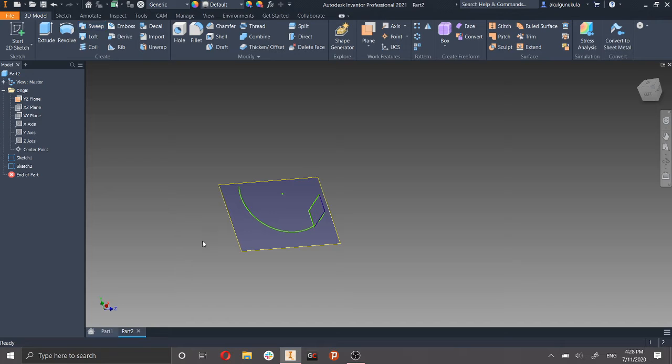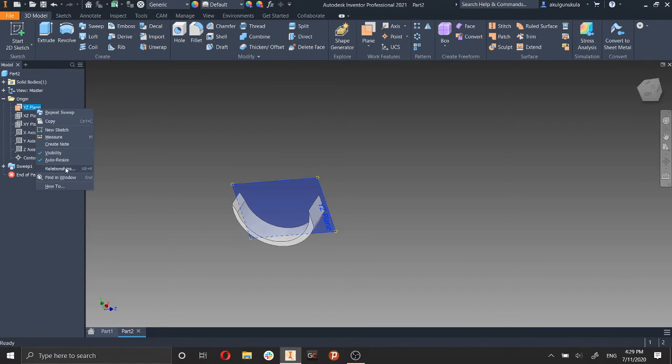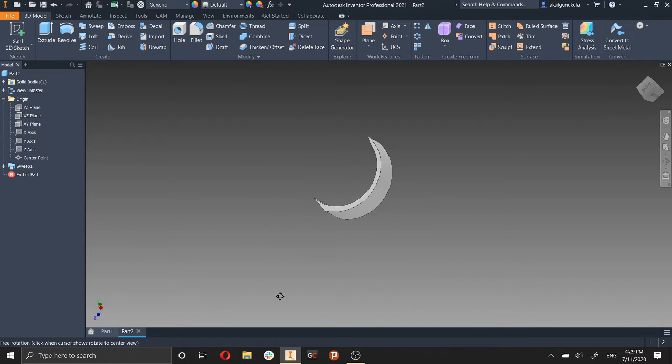So now let's talk about the plane. Oh yeah, let me just extrude and I'll take that away. I'll take away this plane. You can just right click and visibility off. Uncheck it. And there. It's a sweep thing. We use this in FRC. I mean, I've used it when creating bumpers. It's a pretty neat tool. Just dragging along a certain path with the given dimensions.